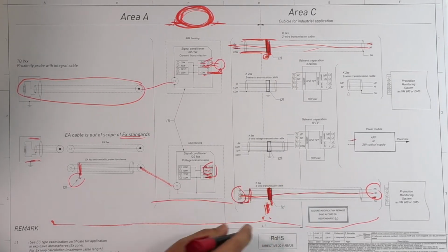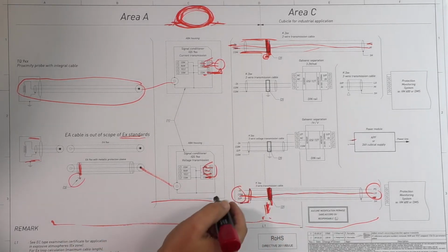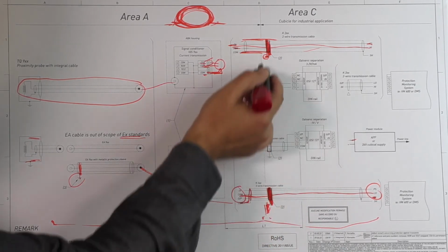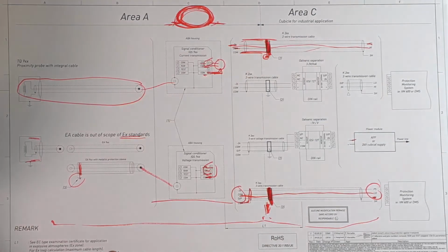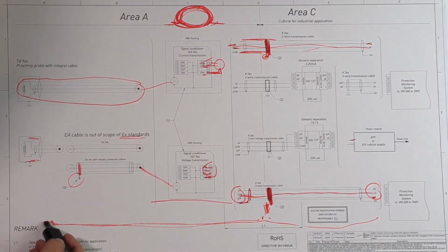The best point to protect your system from non-compliance in terms of electromagnetic radiation conducted as well, is to have a solid ground connection in the entrance of your cubicle. The reason is that the cables in this region, they will be very long.